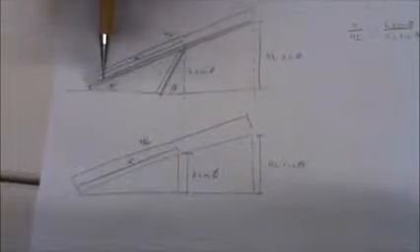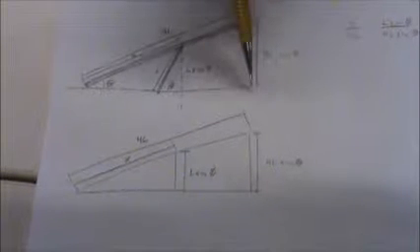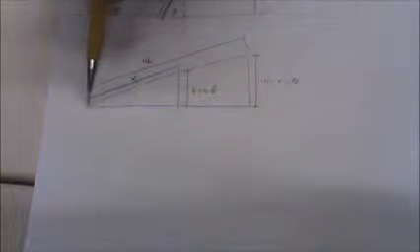And then we're going to use the angle theta back here to do the same thing. 4L times the sine of theta will get us this distance here. Since this line is contiguous and this line is contiguous, we can set up a relationship between x and 4L and between L sine phi and 4L sine theta. That relationship is given in this equation, so solving this will get us x equals L sine phi over sine theta.